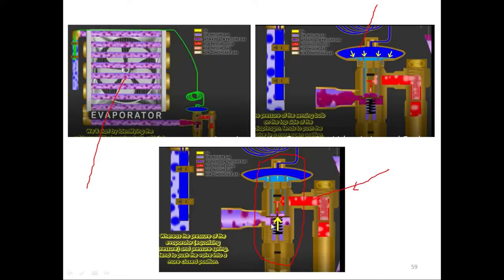In this fashion, we can have more than one refrigerating capacity in the evaporator, or different mass flow rates into the evaporator. So the same evaporator can be used for different loads. This is an advantage over the capillary tube, in which case we can only have one mass flow rate. We cannot change it. We can have only one refrigerating capacity. The cooling produced in a capillary tube type evaporator will be just one, but here we can have different loads from the same evaporator.